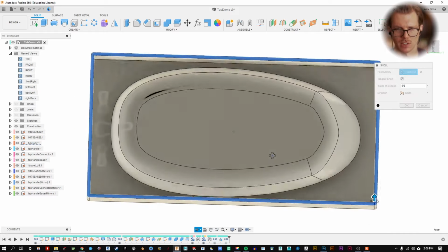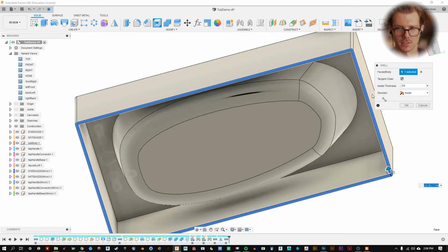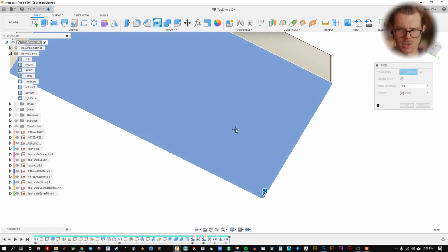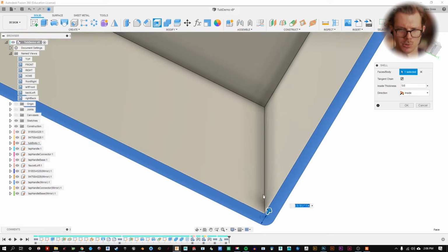So it's really kind of a beautiful result that it's giving us. It took that fillet and it's offsetting that. It takes straight walls, it's offsetting that. What we don't get is that fillet on the outside, these external fillets, they're collapsing to a point where they get sharp, if that makes sense. So if we go 5/8 to a certain point inward, it's collapsing.